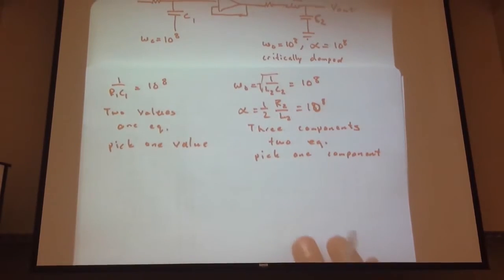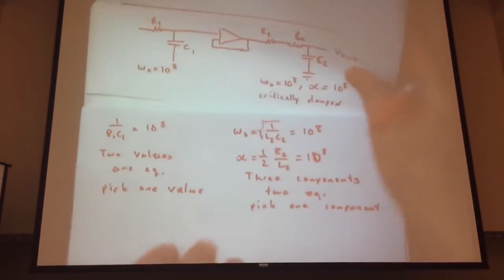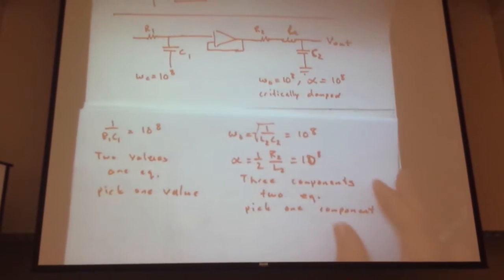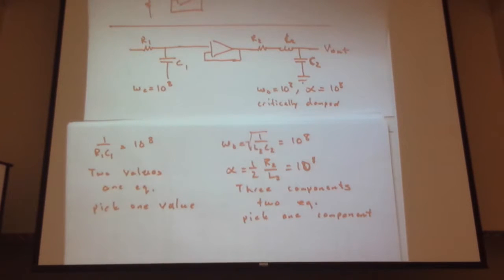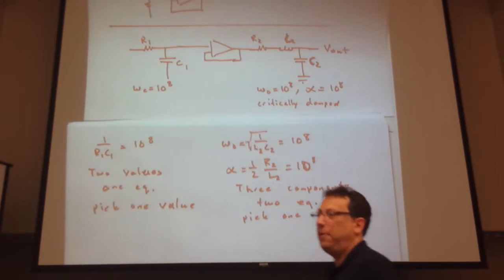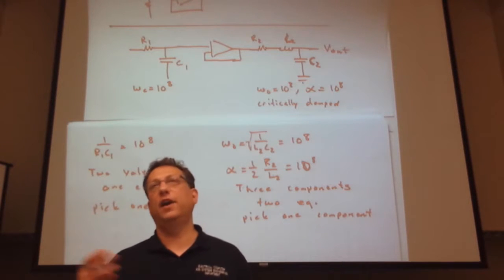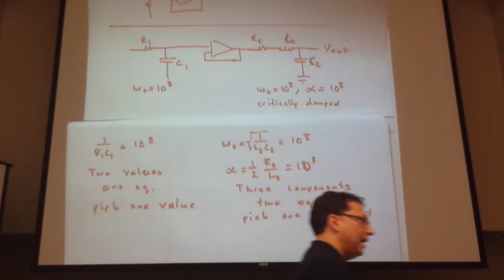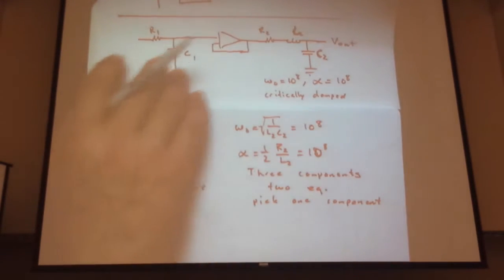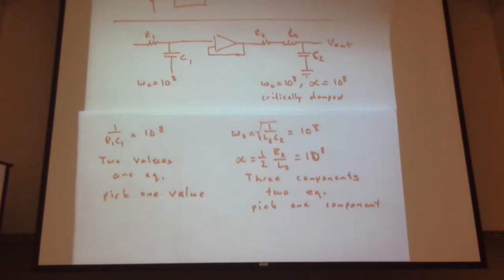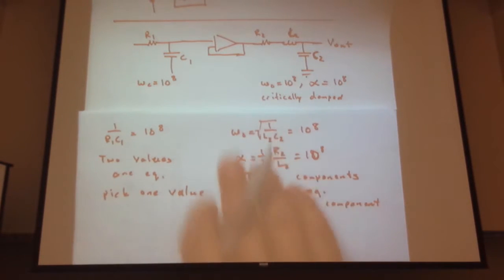So 5-Henry inductors are typically fairly big. You can spend a lot of money and get them smaller, but more often than not, they're big. So there are practical considerations, certainly values that we think about. Picofarad for capacitor up to 1 millifarad, very easy in a laboratory setting. Outside of that, you can spend a little bit more money to get parts, but as you get into the 10 farad range, they're pricey and expensive. On the same token, if you're trying to develop capacitors that are very small, 10 to the minus 15, it takes precision machining, precision calibration.